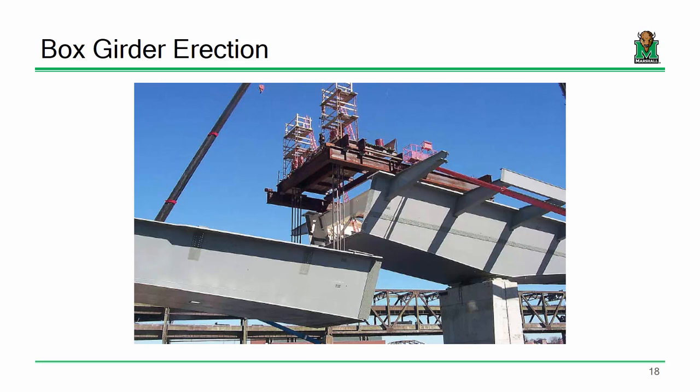And this is just the erection. Again, same questions we've got to answer. They come in pieces, and we're going to have to splice them together. Where do we place that splice so that we have an efficient construction process? And sometimes there is no simple answer. I mean, you've got to consider shipping considerations, material availability. Stuff like this are questions that civil engineers need to answer. And sometimes there's no great answer. There's a bunch of bad answers, and it's the least bad. So sometimes it is what it is.